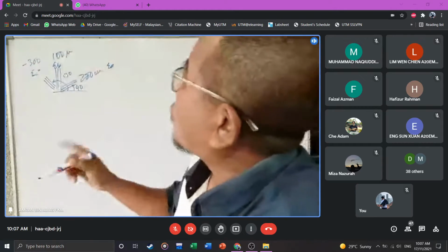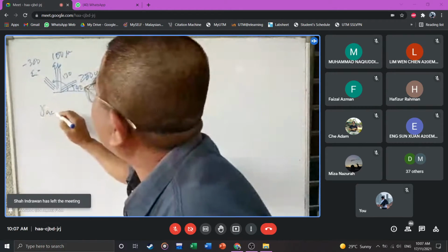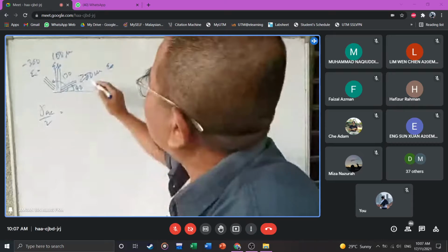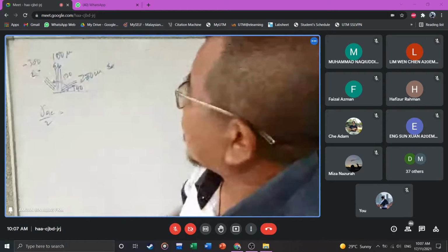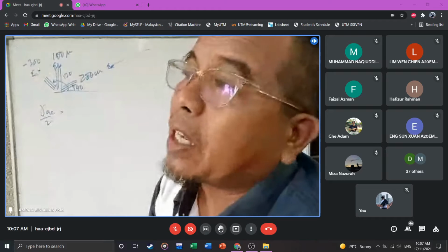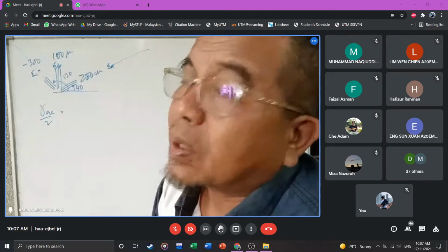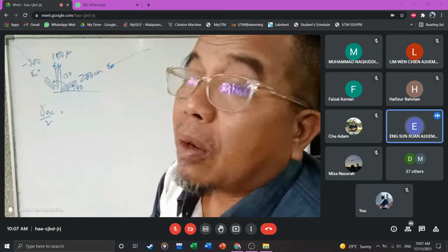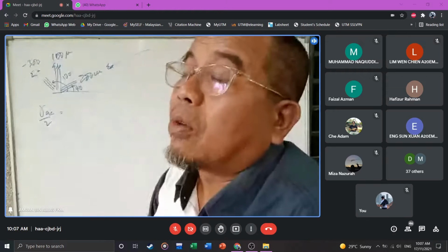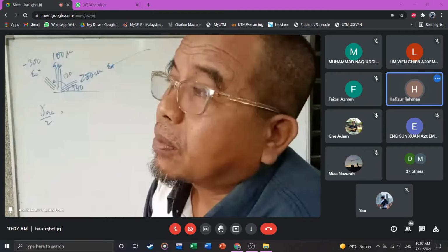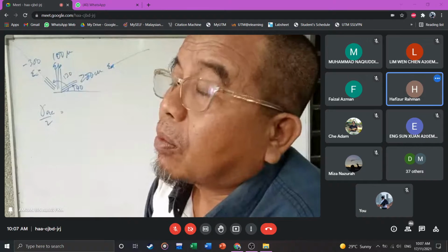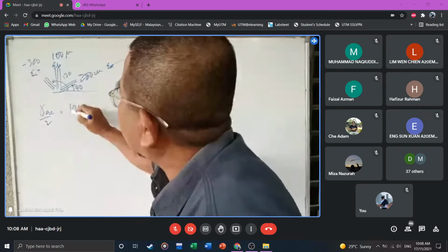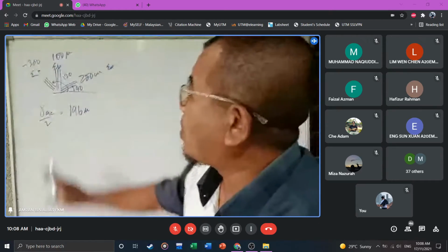So if I solve for gamma AC over 2, I use A here and C here. What is gamma AC? I didn't do gamma AC in your homework. You can read that from the Mohr circle: 196.4 microstrain, positive. Gamma AC over 2 is 196.